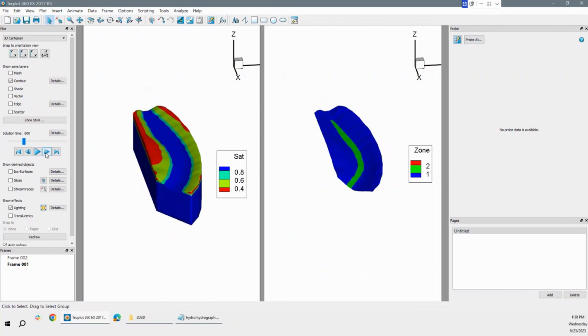You can see that a rainfall event is occurring, and the saturation is going up through the whole domain. And now it should reach top saturation here. So you can see the fully saturated part is gaining, and I think we almost got rid of the red parts and still going up. And you see this rainfall event stopped somewhere here. And if you flip through the time, you can see that saturation is reducing again. So it gives you a good indication about how saturation changed in the model over this rainfall event.